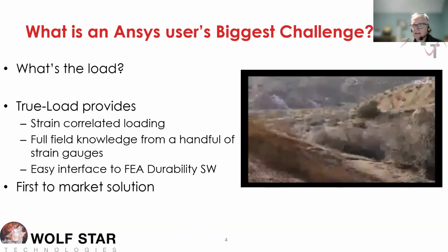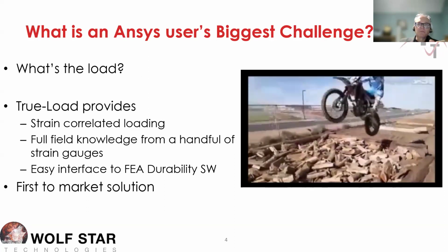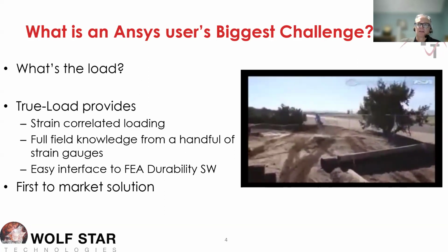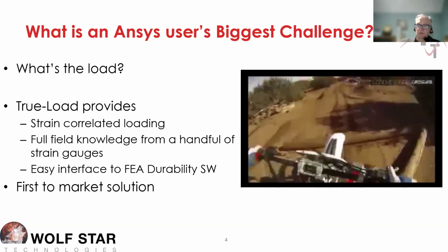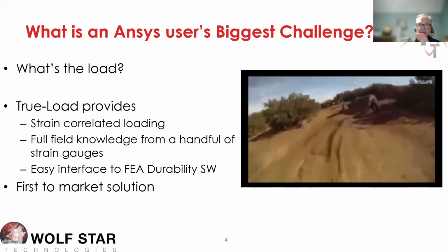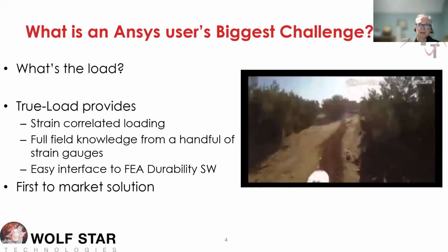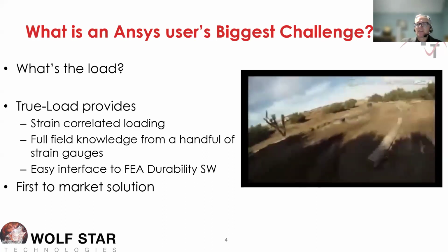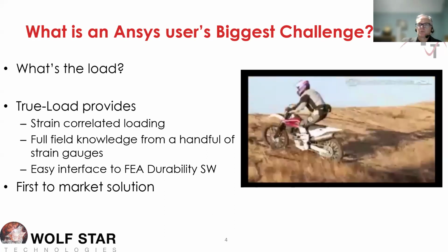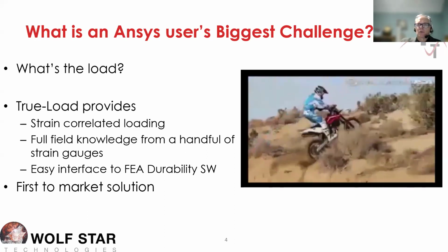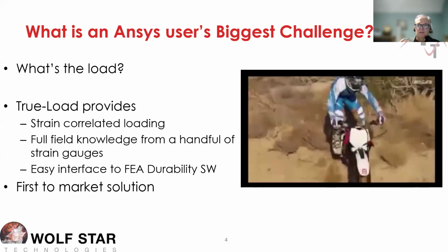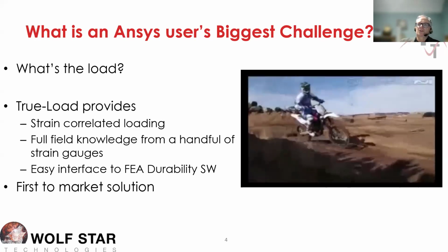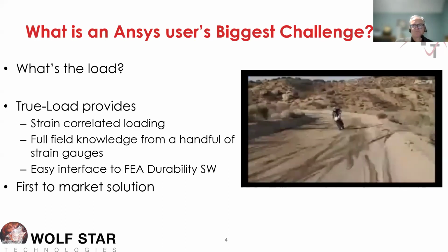It's based on a technology called influence coefficients. And influence coefficients have been around for 50, 60 years. But the problem with influence coefficients historically has been it was all done experimentally. So people would guess where to place strain gauges. They would go through very elaborate structures lab tests to put the unit loads on their parts in the lab, and then they'd end up not having a good correlation matrix. And then they go to the field and they measure the strains, and the loads wouldn't make any sense. And that's just because they didn't know where to place the strain gauges. And what we're doing is we're leveraging the FEA model and scripting to make sure that we get the optimal strain gauge placements and the best correlation matrix we can get. Okay, this is what we're doing.